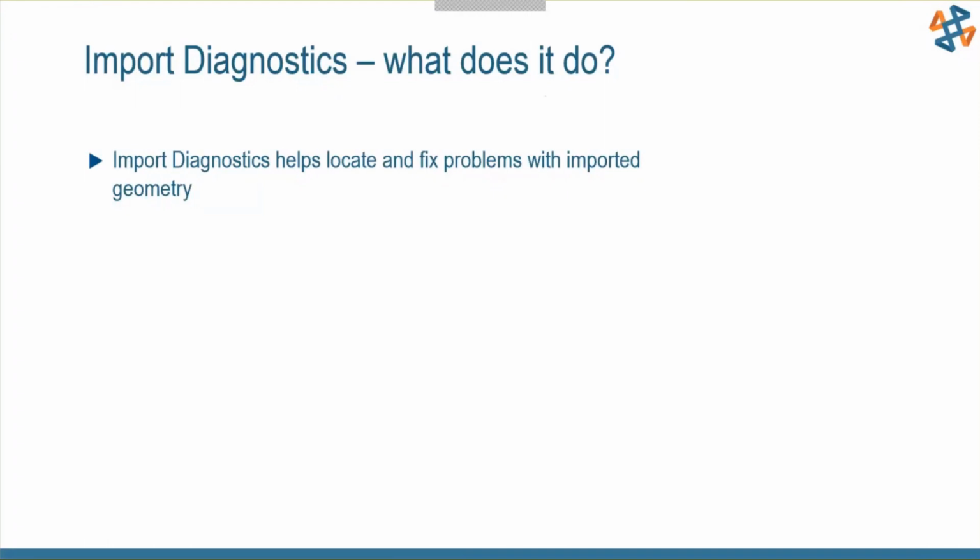So I did get a question in the chat real quick of what is the best curve setting for importing files. And just real quick, the best, quote unquote best, it all depends. Usually that's something that I will adjust. It all depends actually on the import diagnostics. So using the import diagnostics as a tool to make sure we get good clean geometry that comes in. And you can use the curve settings or the different import methods to try and minimize the amount of work you have to do with getting clean geometry.